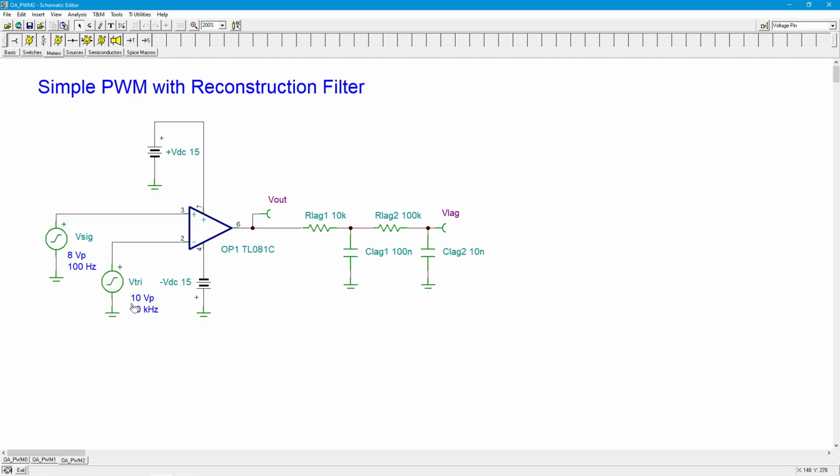And then the triangle wave obviously would have to be several times that, maybe a factor of 10 or 25, depending on your design. You wouldn't use literally this circuit because these resistor values are far, far too big, but you would have to have some kind of filtering network before you actually got into the loudspeaker, right?